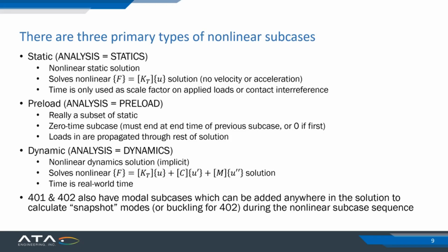Additionally, 401 and 402 do have modal subcases available within them, where you can basically create a snapshot modes simulation of the current state of the model where that modal subcase exists, or even for 402, you can do a modal buckling type subcase and see a linearized tangent stiffness matrix buckling solution for the current nonlinear state. So it's basically a normal eigenvalue buckling type solution, but it's about the tangent stiffness at the current state of that nonlinear sequence that you have been proceeding through in your solution.